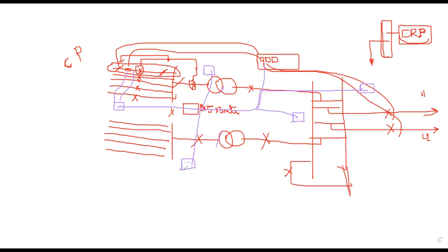If you analyze both the options, obviously this decentralized architecture is a good option for present scenarios. If you want to decrease the cable cost further, nowadays we can see digital substations, where there is no need of cable and only a few cables are coming. That is also a good advantage of digital substations, which most of the developers are focusing on at this point.